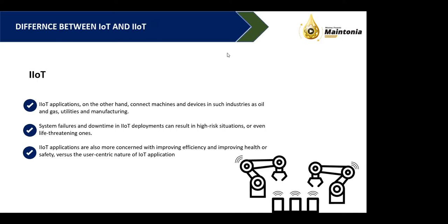And if you touch that notification, you get that one of these parameters is not in the set range or not within the limit. Immediately we can take action, we can make a call to the related person. Suppose machine vibration level is not in line. Immediately we can ask the C&I guy to go and check physically whether the sensor is malfunctioning or it is the real problem. After that, we are comfortable. This is the concept behind this IIoT.